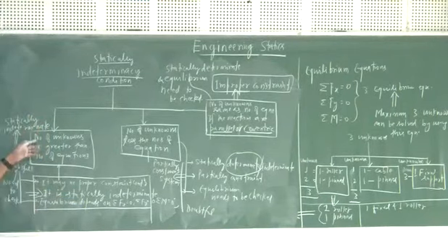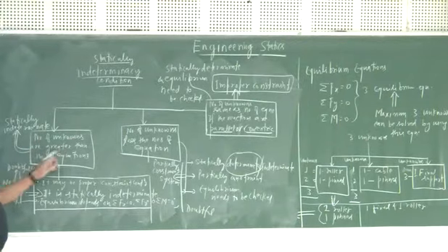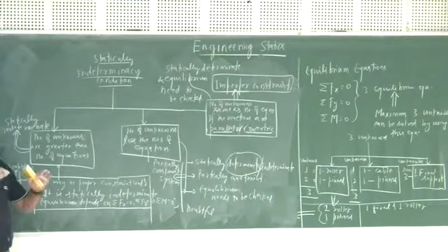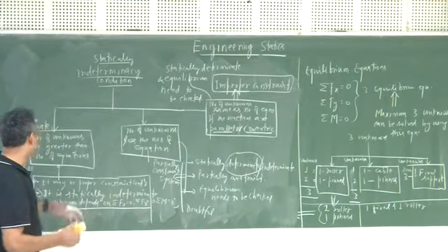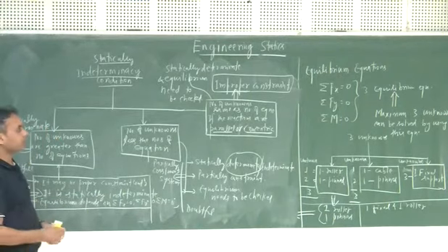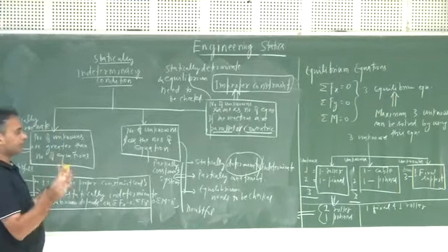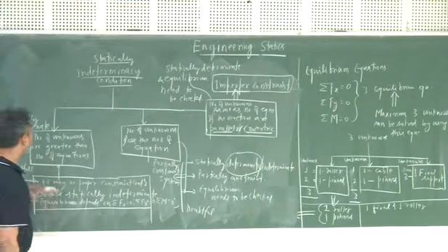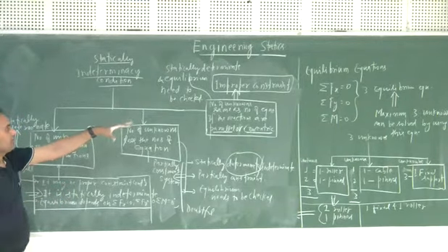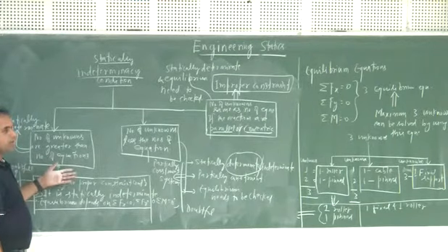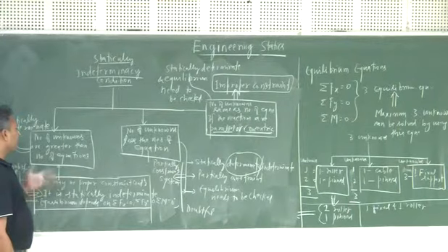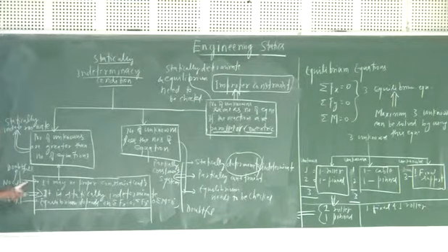So when the number of unknowns is greater than the number of equations, the constraints may be proper because they provide complete constraint of your degrees of freedom, but you will have to check whether it is proper or not. That has to be checked later on.